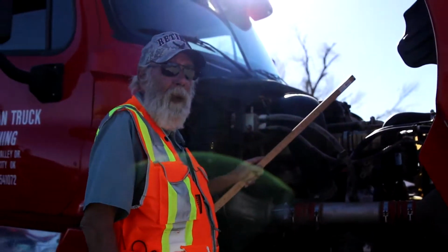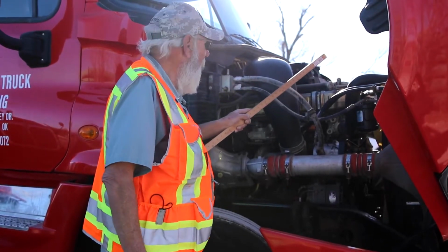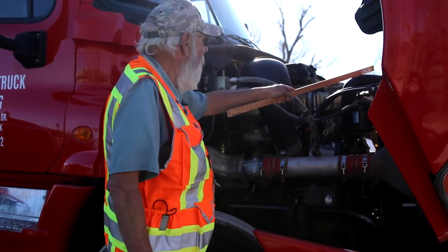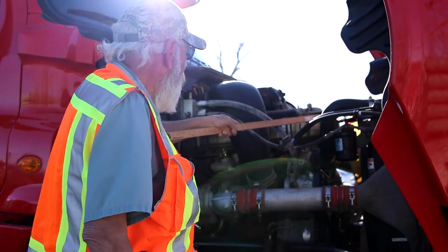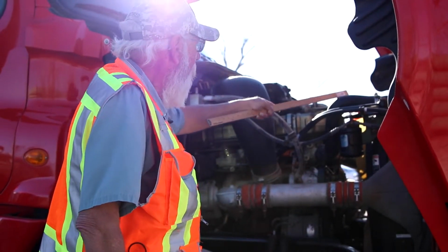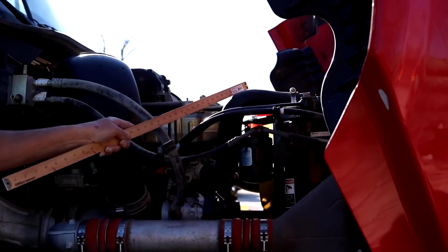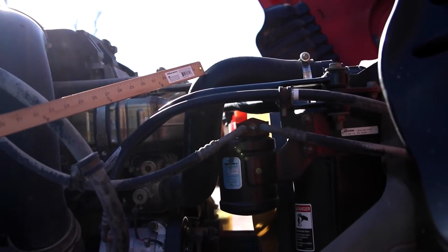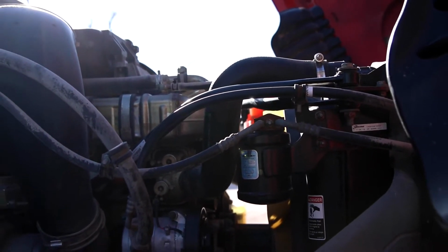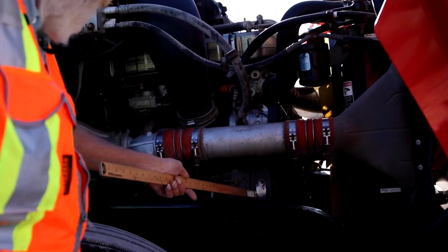Always start at the top, work your way down, go from the inside and work your way out. So here at the very top, your radiator line, it is mounted securely with clamps. There is no abrasion, bulges, and cuts, and no leaks. Whenever you have a fluid or air inside something, you always want to check for leaks or for audible leaks for air.